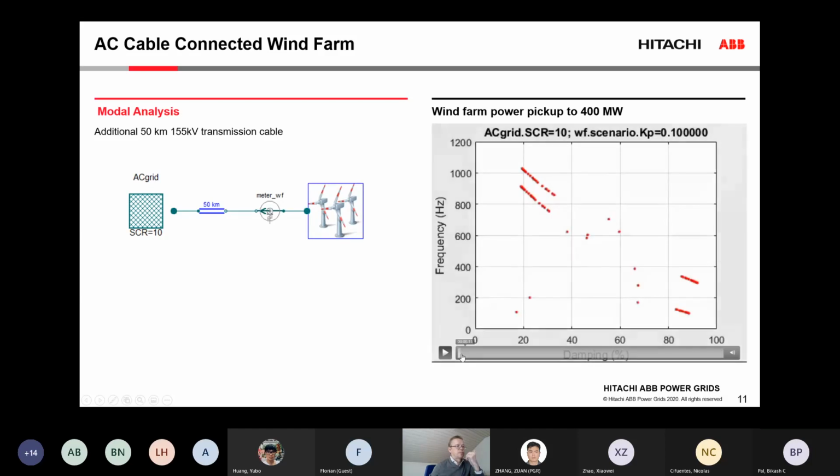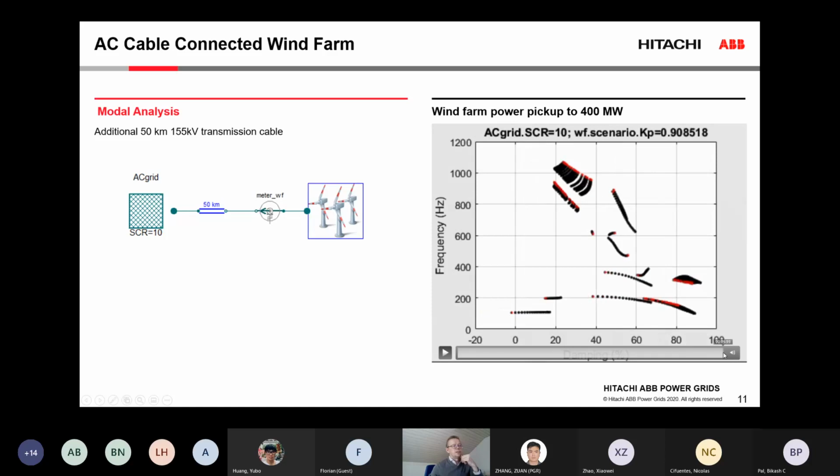And so if I start here in the base case with very low production, so 10% production, it still looks nice and stable. But if I increase the production, we see the grid resonance gets worse and worse. Firstly, they start from a lower base damping, but also eventually we can predict here an instability at around 90% production.